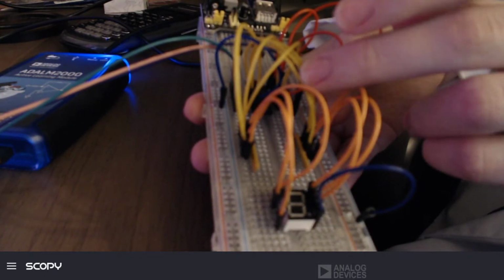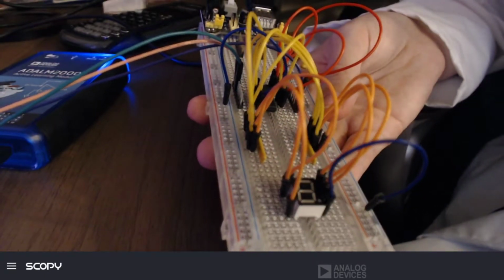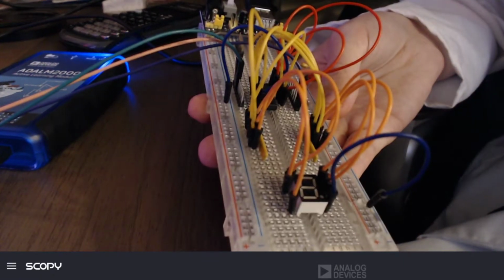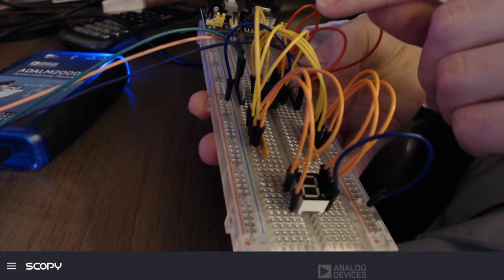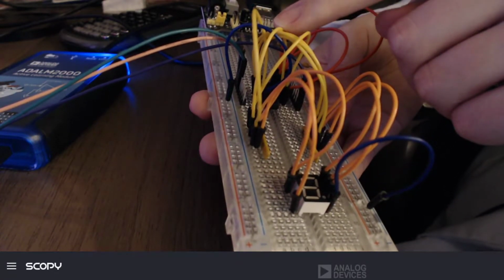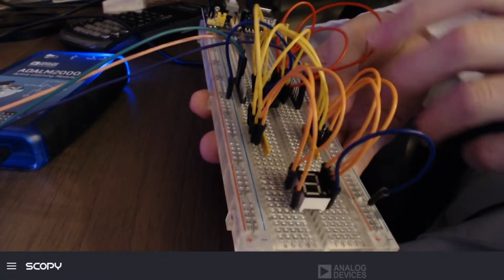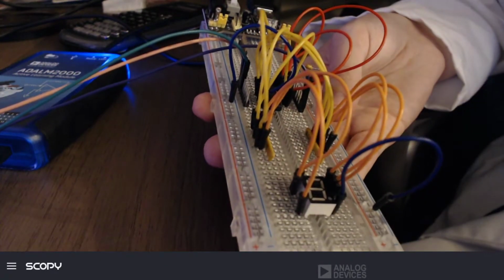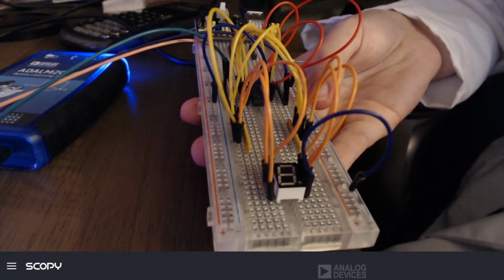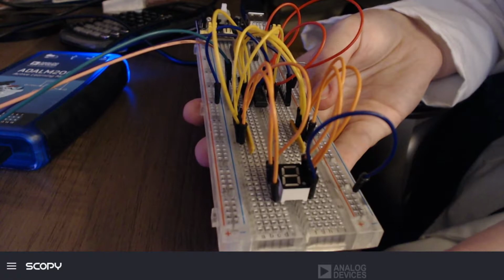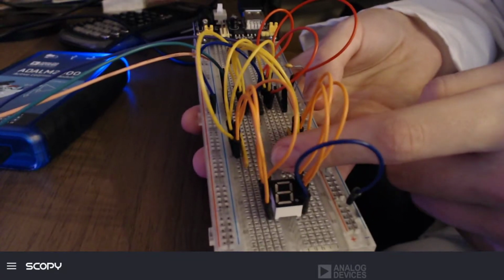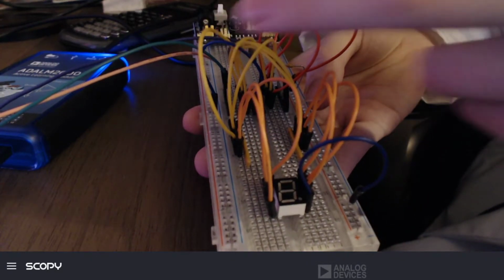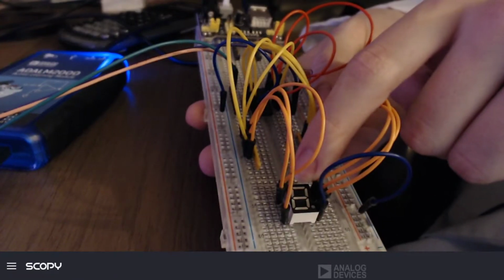On the left, yellow cables consist of A through D, and then cables A, B, C, D, E, and F. We're going to skip G and H. G and H won't be used in this lab, although, again, the shift register technically will shift up to the output G and H. Using 270 ohm resistors, we then will push our outputs into our display.